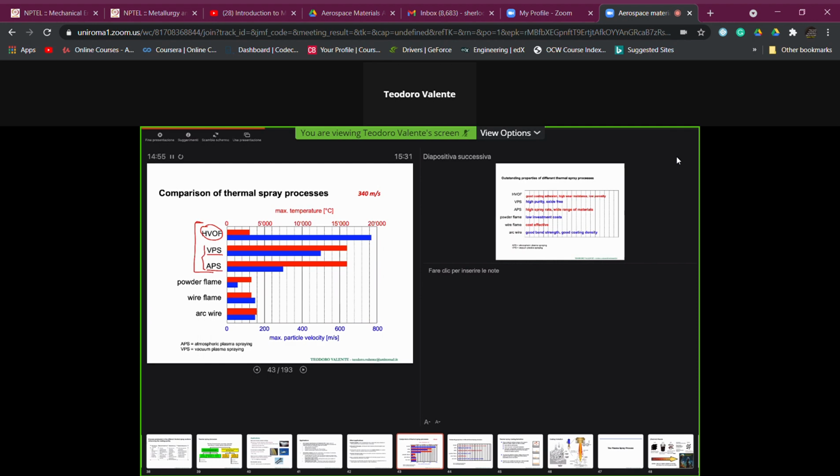And thus, if we need to spray, for example, ceramic materials, oxide-based ceramic materials, for example, partially stabilized zirconia, or for example, as written before, alumina-titania powders, our first choice, if possible, and this is possible due to the figures that we will discuss now, is not to use the vacuum plasma spray technology, but to use the air plasma spray technology.